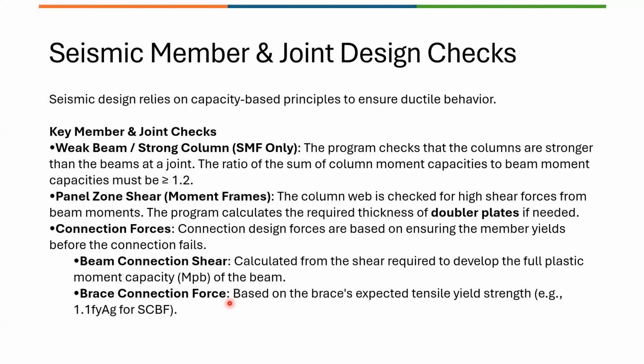It also checks for the joint design, and it reports these outputs. For example, weak beam, strong column for the special moment resisting frame will be reported.